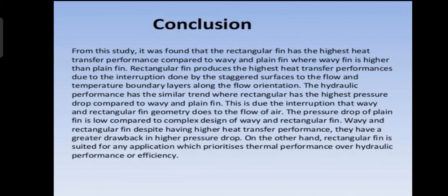Wavy and rectangular fin, despite having higher heat transfer performance, have a greater drawback in higher pressure drop. On the other hand, rectangular fin is suited for any application which prioritizes thermal performance over hydraulic performance or efficiency. So this is all about the types of fins and advantages.